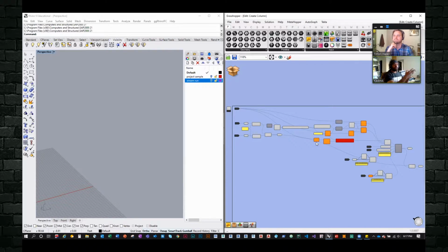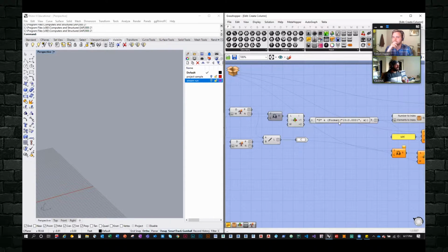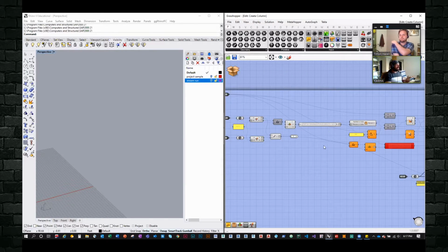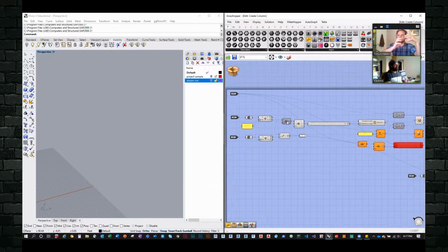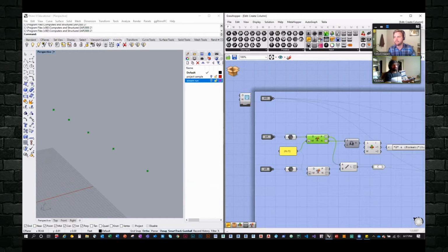I have these tools that I go and retrieve an item from the shopping cart as I need while I'm building the script. What's inside these scripts are some basic expressions, and some that have nested clusters that are even simpler. And there are some that have C# or Python scripts, but 90% of them utilize native Grasshopper nodes. So you've already put something in there that's like draw the line and connect the points, and all these things inside there just generate the column. I think that answers the question on the chat.